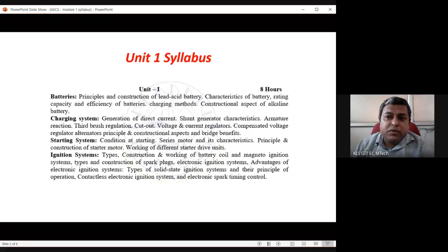Okay, so if the input voltage is anything in between 4 volt to 8 volt, the output voltage of the regulator will be 6 volt. Is it understandable? Always try to understand things simply. In books, a lot of things are written, but you people cannot interpret. So in the initial lectures, I'll be opening the things up like this.